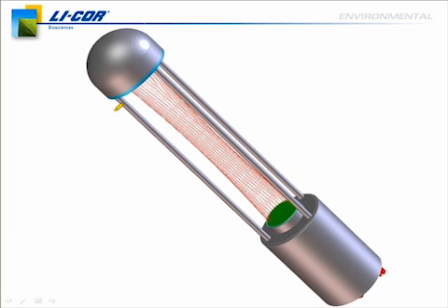At the top we have an optical source and a detector. There's a mirror here, and there's a mirror at the bottom, and these red lines in this CAD drawing represent the laser path. Now there's an infrared laser source in the instrument, so you can't actually see it, but this is just a representation to give people an understanding of what the path looks like. So we've got these 2 spherical mirrors that make up the Herriott cell, and they're placed half a meter apart, but they have 60 passes of the laser.